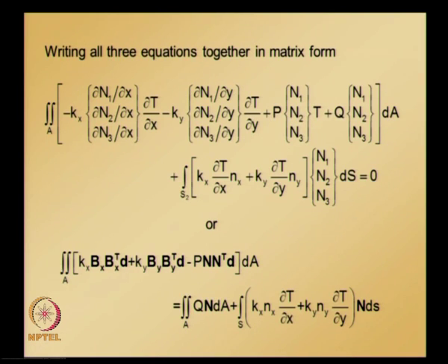And the integral value over S1 is unknown, since along S1 essential boundary conditions are specified, and also this term, the integral over S1, as we will see in a while, it is going to show up as a reaction term in the element equations, which we also observed when we were deriving element equations using Galerkin criteria for one dimensional problem.